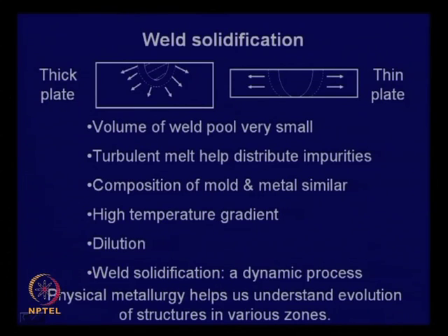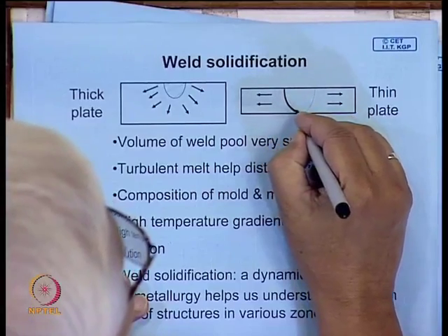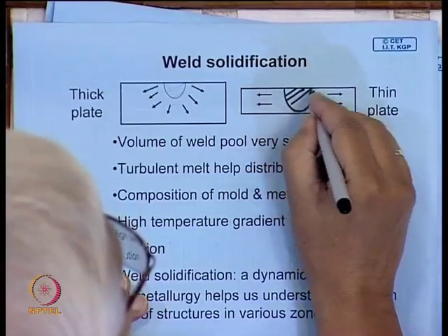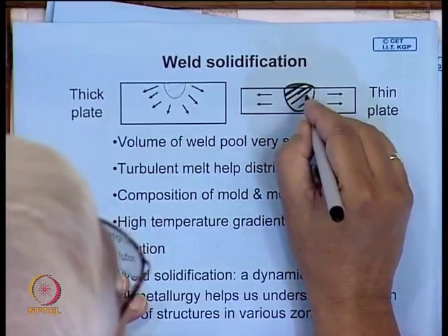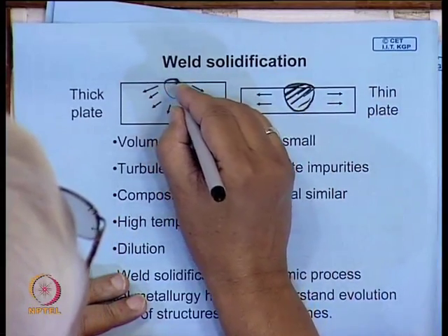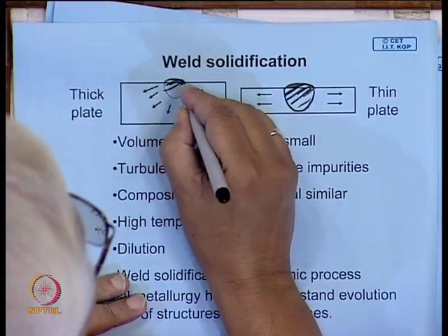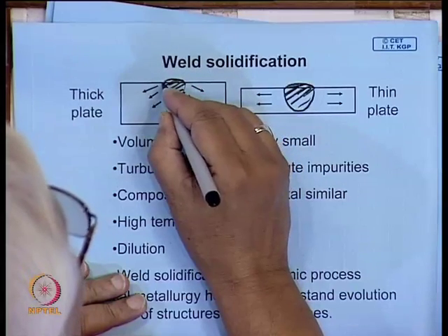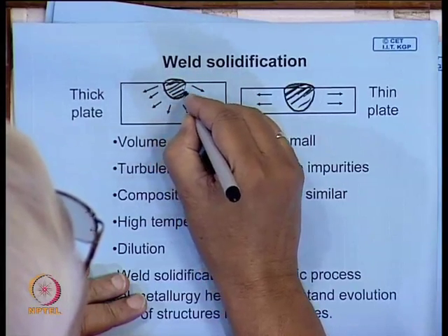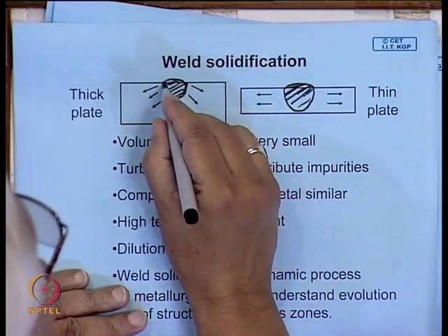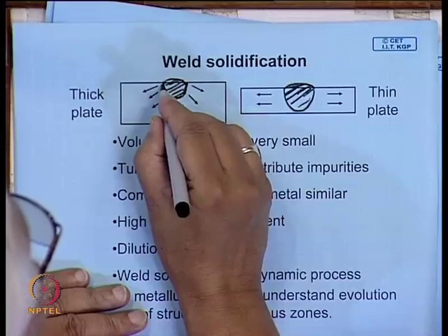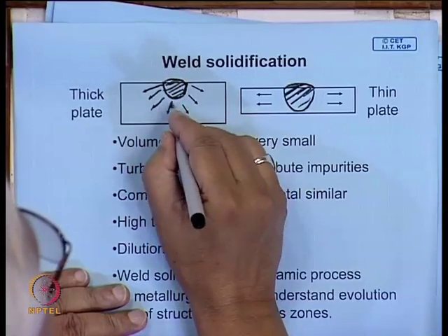We will just look at this here. This is the molten pool. In fact, this will be slightly raised. Here also this is the molten pool. A thin layer beneath this solid will also melt, and in this case, beyond this fusion zone, heat can flow in all possible directions.